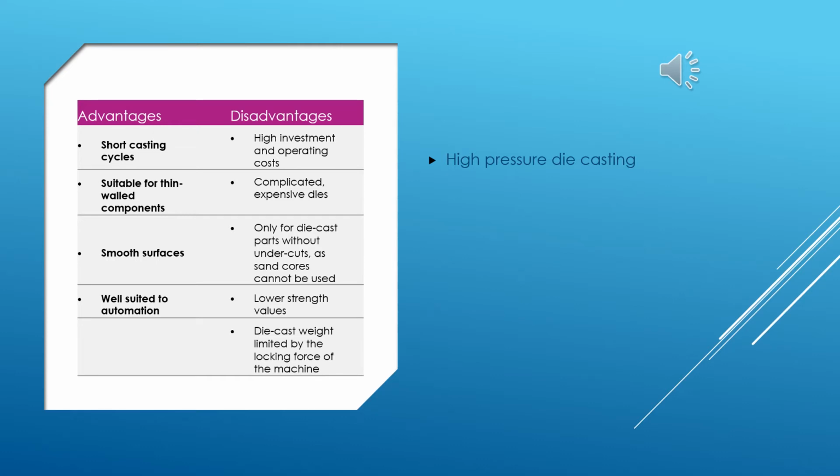Based on those advantages, the mass production sector was focused to continue with high-pressure die casting because of its extremely fast cycle times. The fact is that a high-pressure die casting machine costs around 4 times as much as a low-pressure system until a few years ago. However, the former's casting cycles were around 4 to 6 times faster.